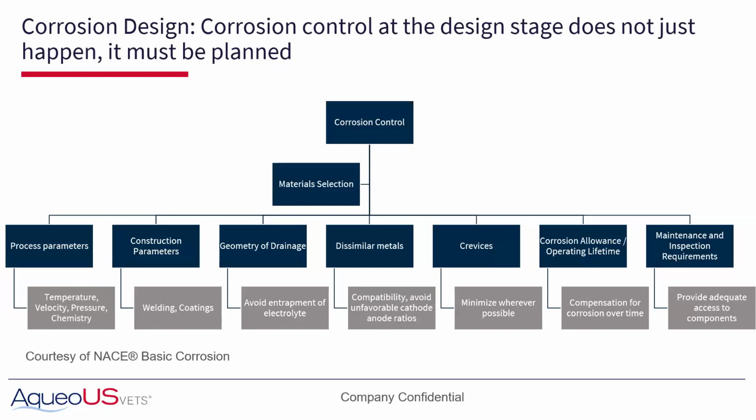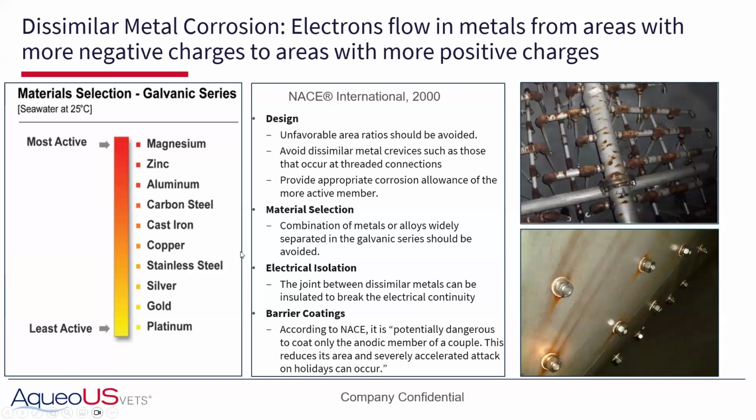And over time, you are going to have some. You're just going to have to compensate for it. So again, we're trying to reduce this. And in inspections, obviously when you're doing a media change out, it's the optimal time to be doing an inspection of the system itself. These are just the galvanic series. Obviously, we try to keep the dissimilar metals apart from each other.